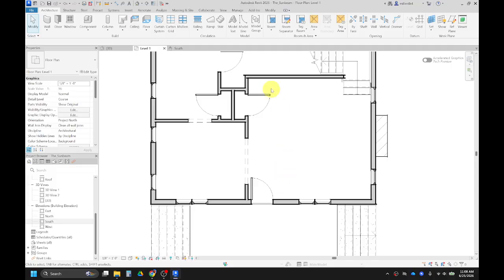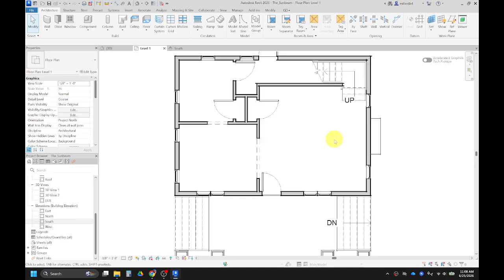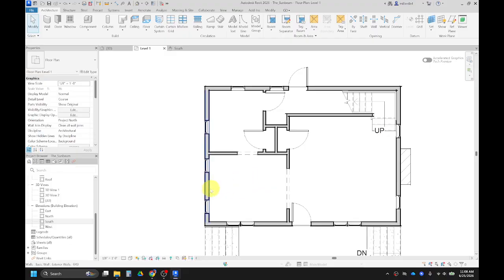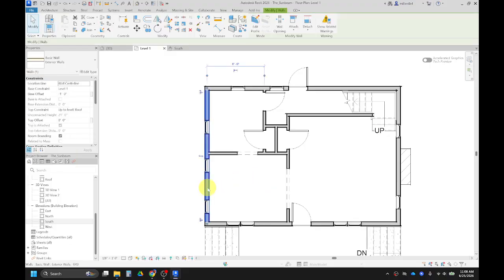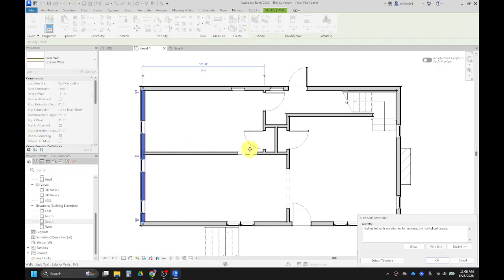The other thing is that Revit intuitively knows how stuff is getting connected in here. So if I click on this wall, for instance, I get information about this wall type. And if I click and drag it out, I'm just holding and dragging it out, it pulled all of those connecting walls with it, and it kept all of my corners attached.